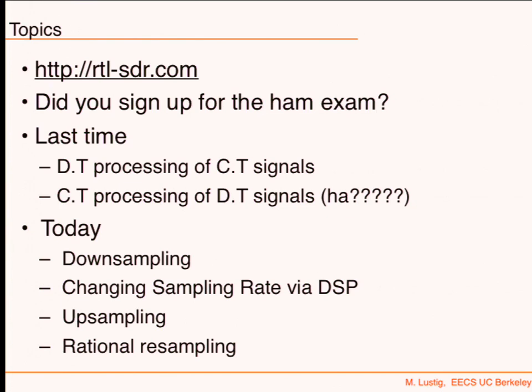It's a chicken and egg thing. You can't do anything without a filter, but for filter design, you have to talk about this. But it's a tool that you're going to be using. The other thing you're going to do is a lot of resampling or downsampling, and so on and so forth. So what we're going to cover today is very useful for the lab, again because the data you capture in the RTL-SDR is way faster than you need afterwards to play it. And so you need to change the rate in order to play it appropriately.